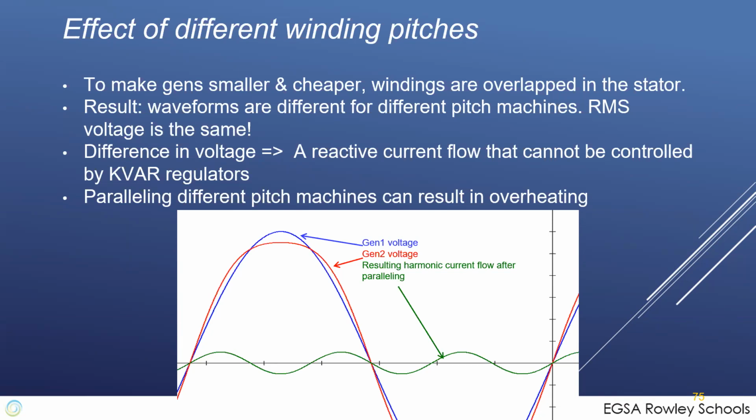So at the peak of A, you've got C going down and B coming up. And so they've laid A and B, and they've laid B and C windings in with the A windings in an ideal pitch, in a one-to-one pitch machine.